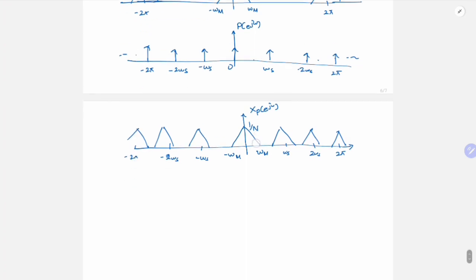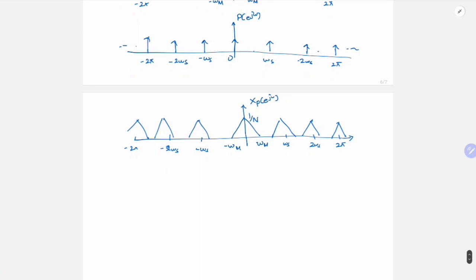And so on. So this is when aliasing does not take place. So if you see this where it is meeting, it is my omega s minus omega n. So this should be greater than omega n, which means that my omega s should be greater than 2 omega n. So this is nothing but my sampling theorem. So you can see here also it is similar to whatever is there in the continuous time case. So if this is not holding true, then we'll see aliasing taking place.